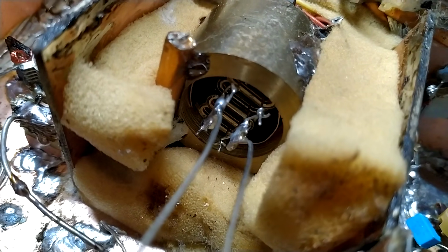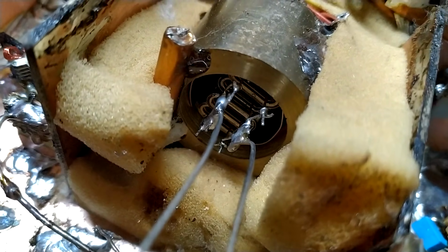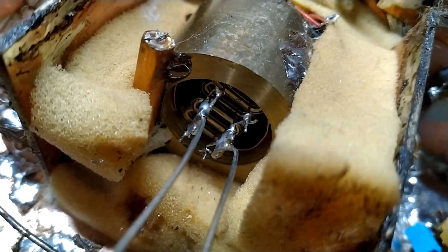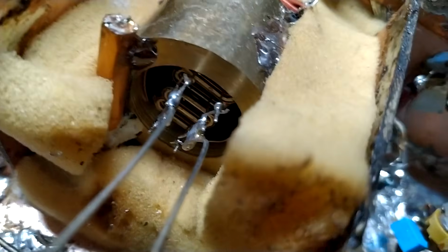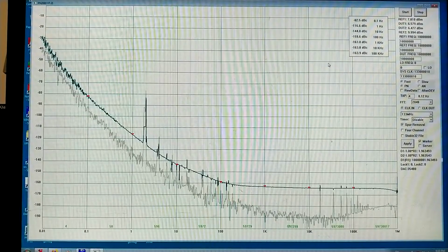Here the 4 crystals are in place in the oven. I will put back the thermal isolation around it. I have tuned the group of 4 crystals very close to the frequency of the Wenzel oscillator, because I want to investigate the unit as an amplifier as a first step.